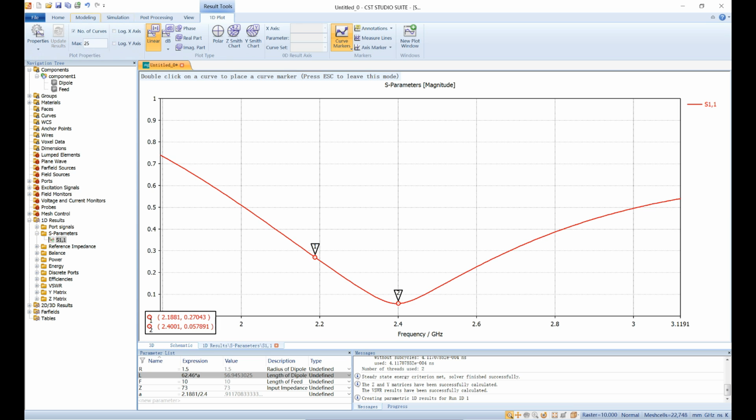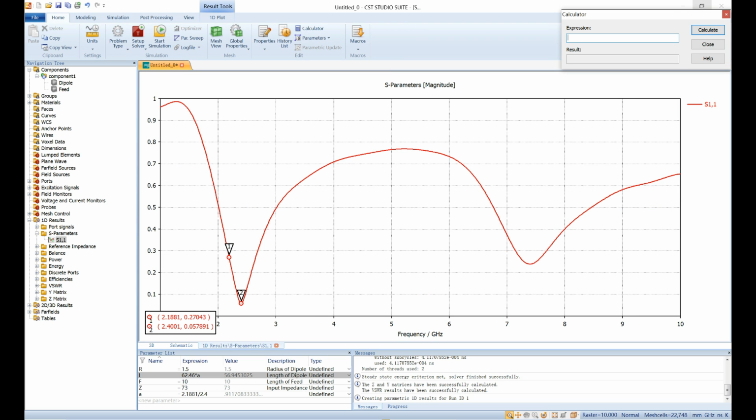We can calculate this value. Here we can see nearly 0.34% power will be delivered back from the antenna to the transmitter, which means the return loss is very low and the transmission line efficiency is very high at the moment.